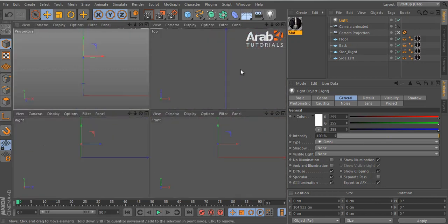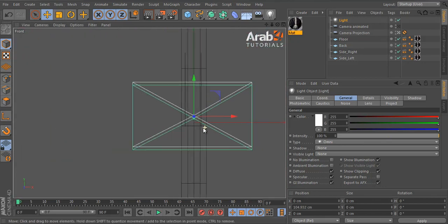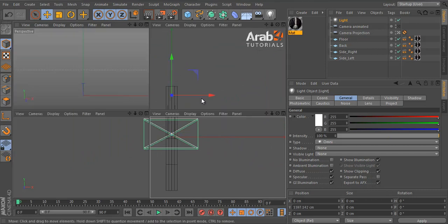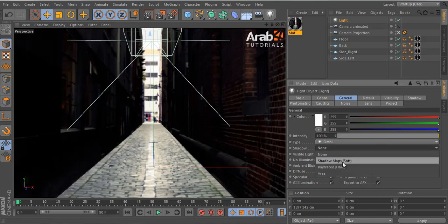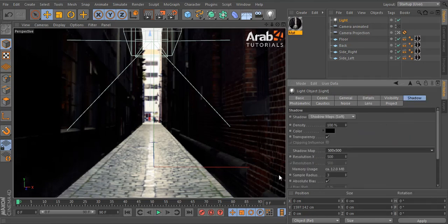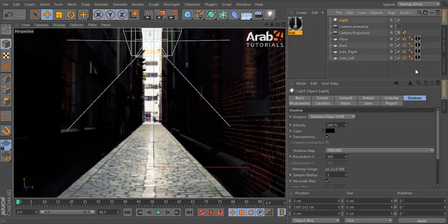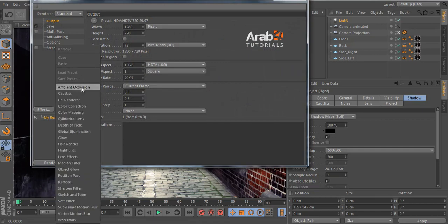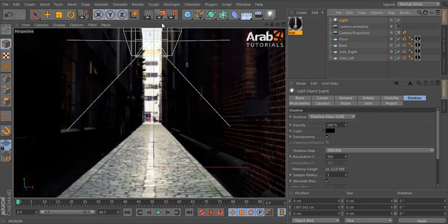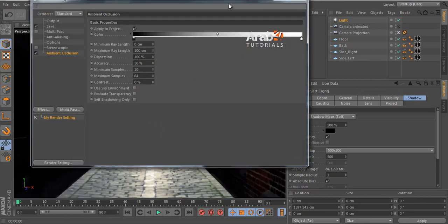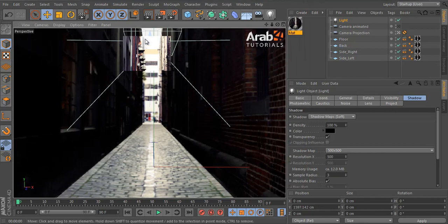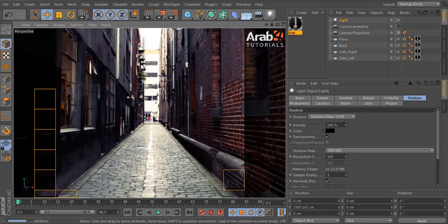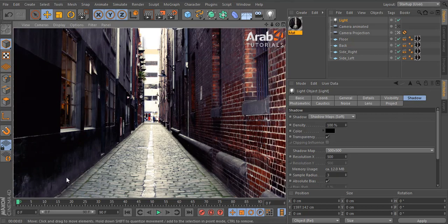Actually, we need to add a light. Only a light, no problem. It's just for the shadows, you know. For the soft shadow, I can make the shadow map about 500 by 500. Let's see. Okay. There is always a problem at the edges of the planes. As you see, there are shadows up there. Actually, if we have an ambient occlusion effect, without the global illumination, it will be darker on these sides. As you see, we can fix this very easily.